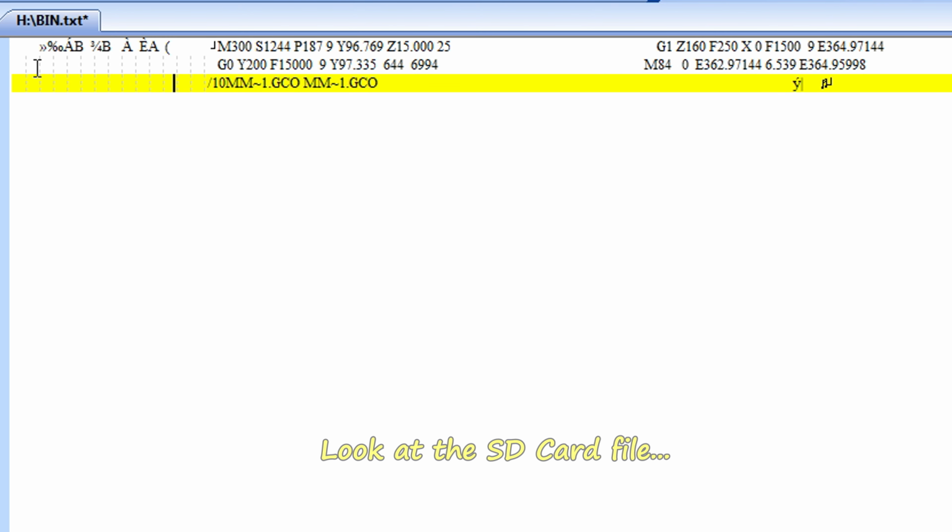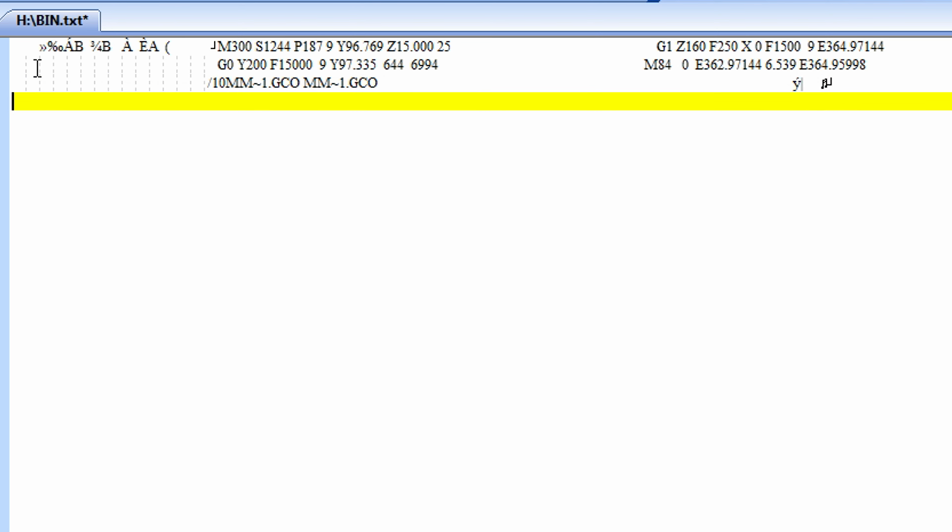Now I'm just looking for Z15. That's layers, don't forget, the layer numbers supposedly, not the height. We've got 0.2 layer height, so we have to halve that. 7.5. Well, by the time I hit the, you'll probably see better on the video, that might be about right. So I'll let you have a look at this a bit.